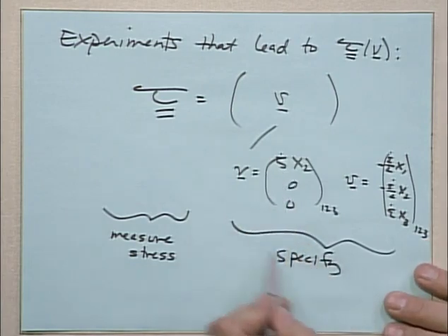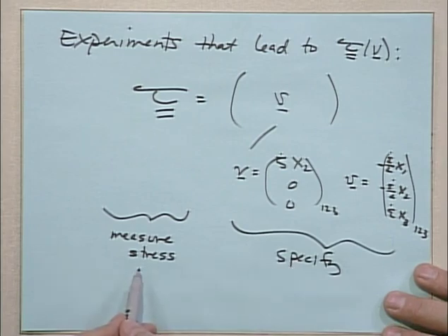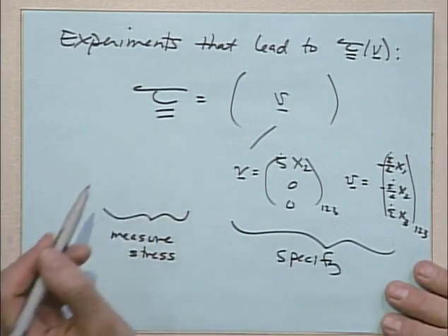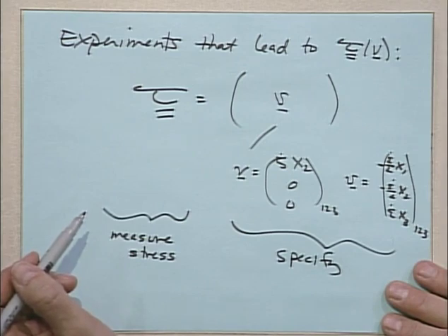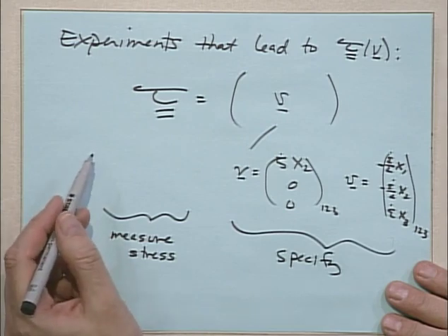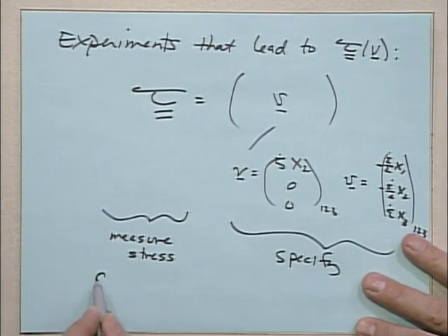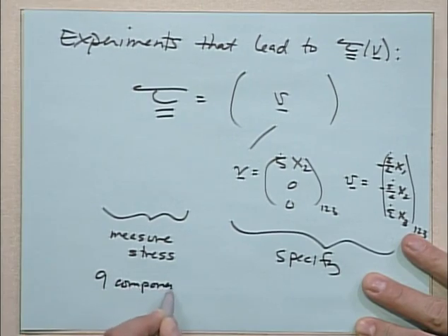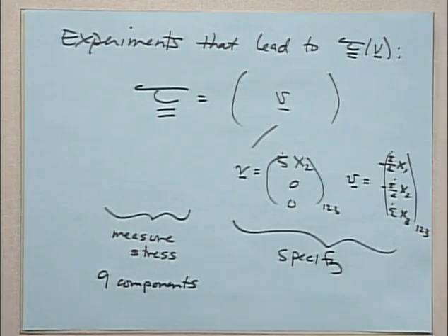We're going to specify the right-hand side of the equation, put the sample in the instrument, and measure the stress. Now, how many components of stress are there? 1, 3, or 9? 9. So there are 9 components of stress. How many stresses do you measure in an Instron testing instrument? 1. You can measure how much force it takes to move it apart, right? Stress is force per area. What area do you divide it by to get stress?